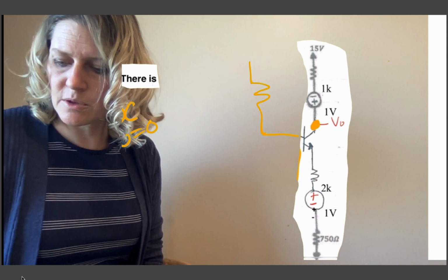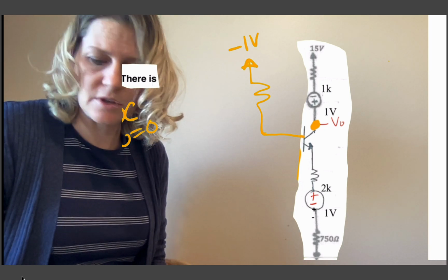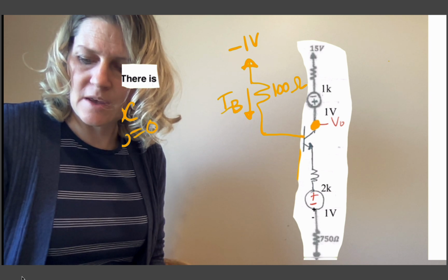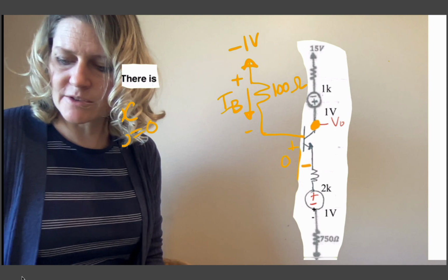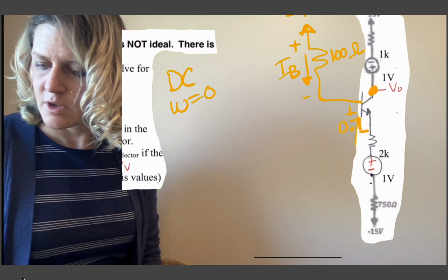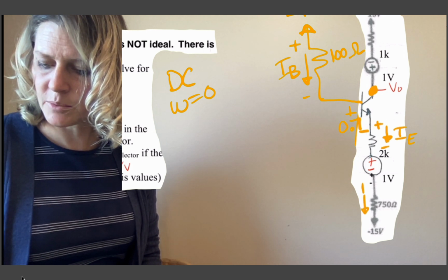And it will go into the base. And so I have the -1 volt and then the 100 ohms. And then this current is IB, which is going to go plus to minus. I also know I have a 0.7 volt drop here. And then the currents through here will be IE. So this will be plus to minus here, and then a plus to minus here.